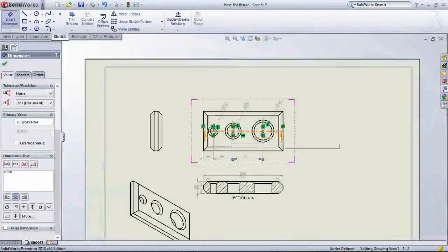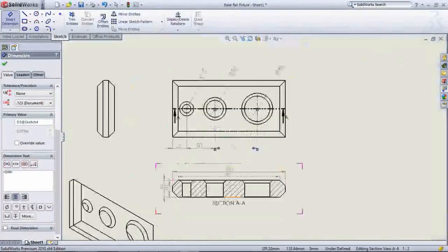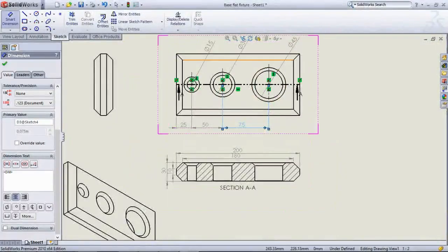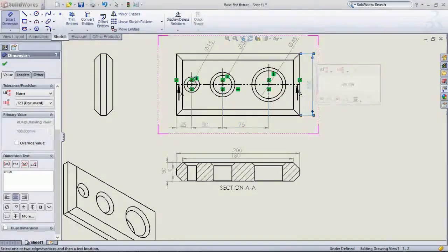These are all the normal points seen from the side of a manufacturer, a production engineer or a machine operator, who will just take a printout of your drawing sheet and view what the stock is. He will check the available stock and place it in a machine, and find the center point of each hole where we are going to put a reference center point.